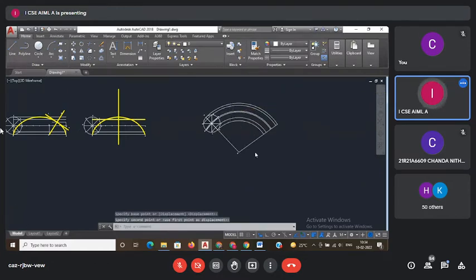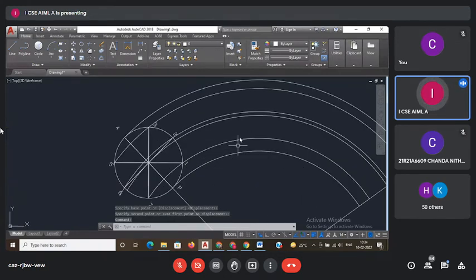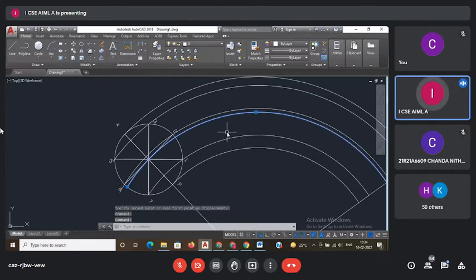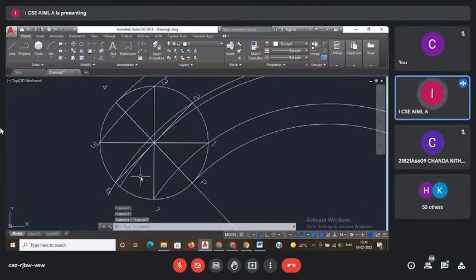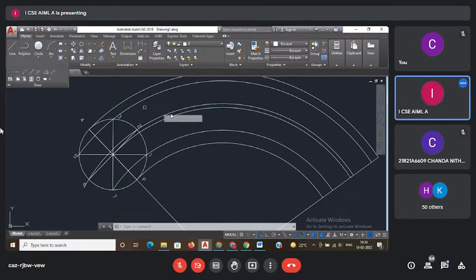Okay. Now see here. Now here the center line you have made into equal parts. Now here the center of the axis is this one. But this axis has not started from the center. From the end it started. That's why remove only this corner by trim. By using trim command, just delete. Now if you observe this circle having center from the center to this end point. Now you have to divide this center axis, this axis line into equal parts. Same procedure from now onwards.